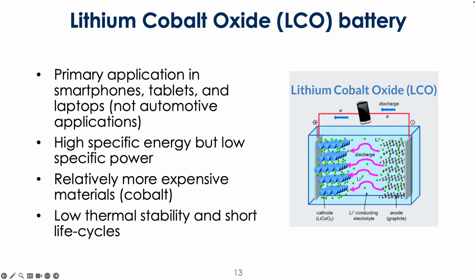Okay, so lithium cobalt oxide, or LCO batteries. These are very common chemistries, used in smartphones, tablets and laptops, but not really in automotive applications. The reason for that is these have very high specific energy, which means I can get a lot of use out of them in a single charge, but relatively low power.